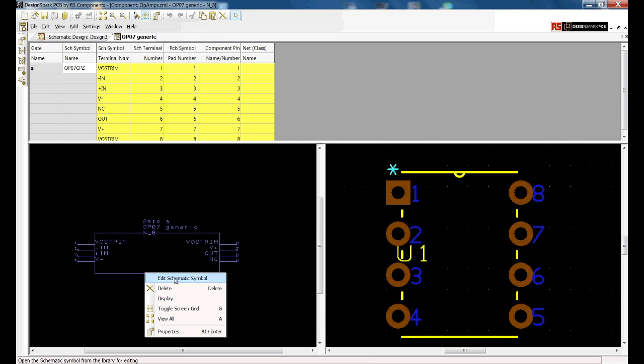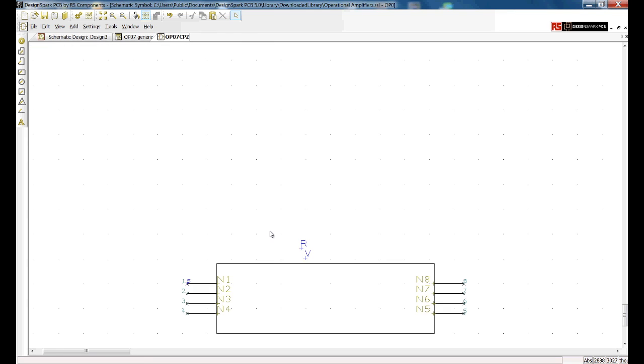An important concept to understand is that it is the schematic symbol terminals that are the most important. The rest is just artwork and text. Let's create our op-amp symbol. Keep the height about the same as the other symbol. For consistency, change the line style to symbol outline.